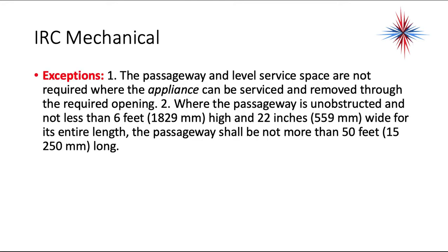There's some exceptions to this rule on passageway and service areas. The passageway and level service space are not required where an appliance can be serviced and removed through the required opening. In other words, if you can stand on a ladder and service the equipment through the opening to the attic, you don't have to have the level service space put in.